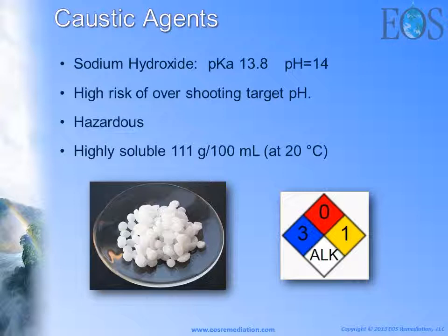The final thing is that caustic agents like sodium hydroxide and potassium hydroxide are extremely soluble, almost infinitely soluble. This is a good and a bad thing. It's good because it makes it very easy to inject these materials into tight formations or just into the subsurface in general. But at the same time, that solubility gives them essentially no longevity in the system. Once you introduce them, if there's any kind of groundwater flow, you're going to get a washout effect and no residual pH adjustment from these materials. They're going to get washed out, and then you're going to be left with a rebound of acidic conditions.